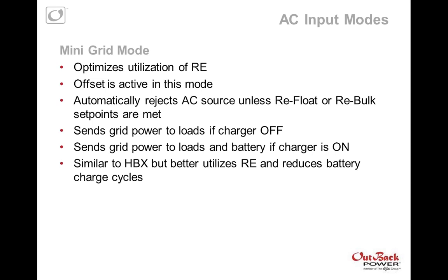There was another quick question there, Mark, in regards to the UPS mode. You there? Yeah. It was basically wondering whether it was like a true UPS with double conversion or whether it had a 4 millisecond interval start time. The double conversion part, I'm not sure of, but I do know that with loss of grid power, we are able to switch over within 4 milliseconds.